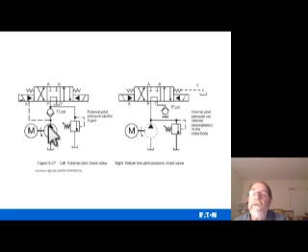Then here you have a check valve, keeping fluid from coming back into the pump, but you also have this relief valve system. So if you have so much pressure buildup, right now at this position it's putting fluid back into the tank.